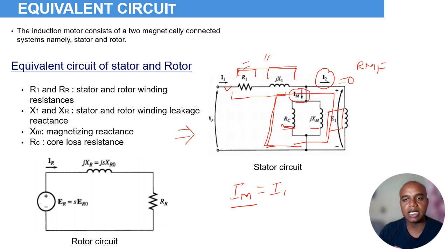It is just like the transformer, where if I want to establish the flux, my windings are placed over the magnetic poles, which are modeled in my motor. Those poles are made of a material that accounts for some kind of resistive loss, so that is accounted for as a core loss.